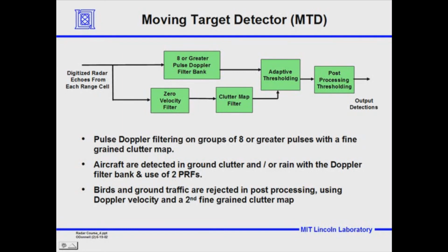And the adaptive thresholding would be on that whole area. It wouldn't be on a specific range-azimuth cell, because you didn't have the power to do it. It was also a time when we weren't really understanding that hardware and software and the algorithms needed to get together from a solid systems engineering point of view and work together in an integrated fashion.